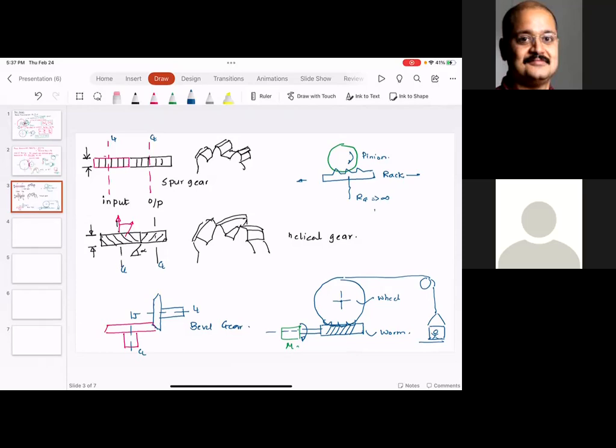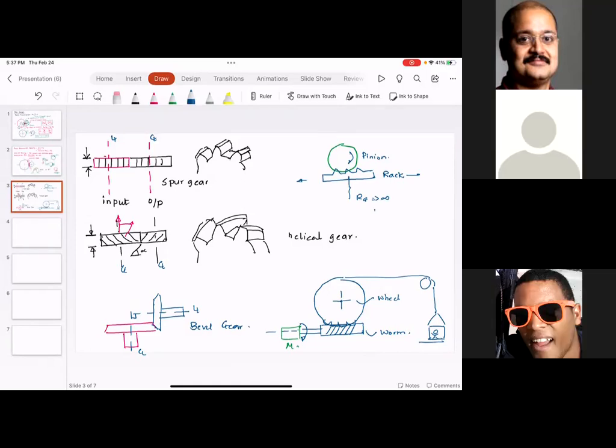So depending upon what you desire, the lubrication can perform cleaning, reducing the amount of friction, reducing the heat. Sometimes the lubricating oil would transfer the heat. In the case of, for example, automotive transmissions, if you notice, the transmission oil runs through part of the radiator, that is where the transmission oil is cooled. And that cool transmission oil is fed back into the transmission. So oil would dissipate the heat as well.